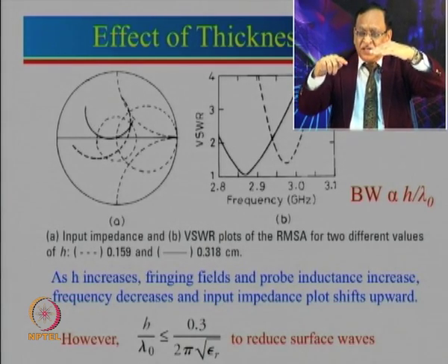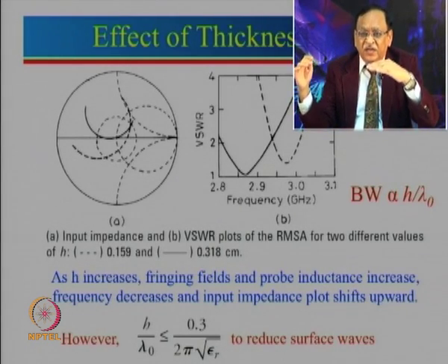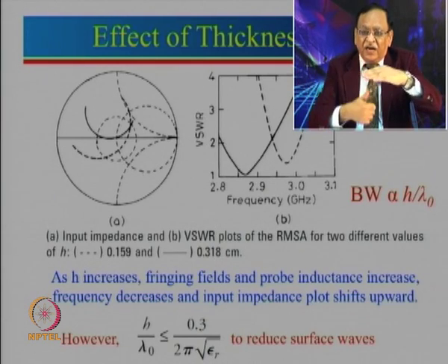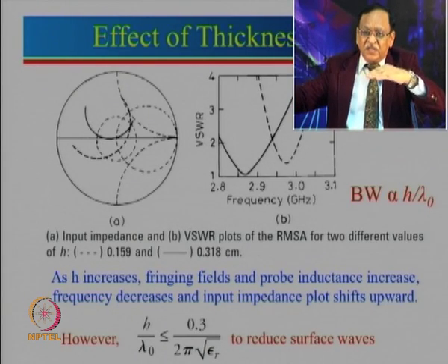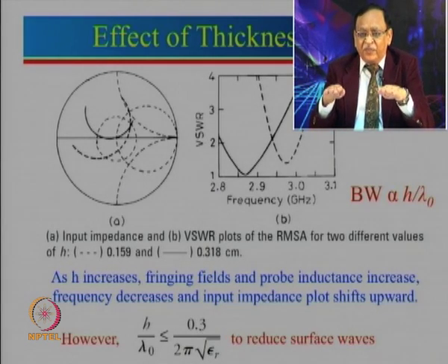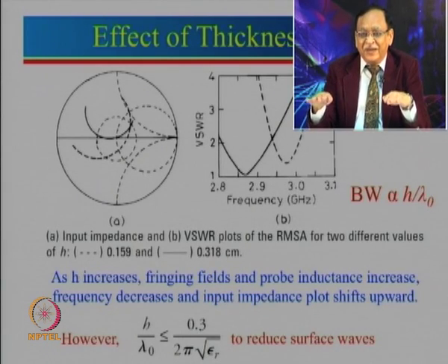So, what happens then, this radiation is towards the surface, and that is not the desired direction, because we are designing the antenna right now for broadside, and here the propagation is towards the surface wave. So, that means energy is getting wasted. Also think about arrays, if we are going to discuss them when we start doing it.